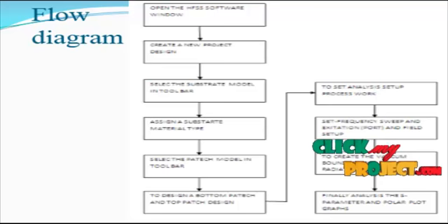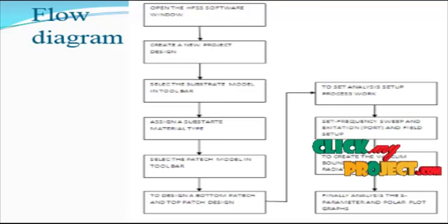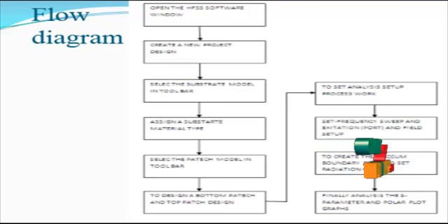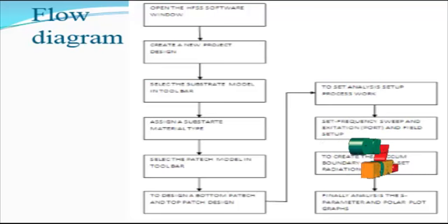We implement the antenna design using the HFSS software. This high frequency structure simulator handles the frequency development and the bandwidth calculation, and all the designs and developments are included in the HFSS software. First we open the new HFSS software and create a new project design in our 3D model based designs. First we choose the substrate model, and analyze the substrate model, the dielectric constant value, the permittivity value, and the dielectric substrate modeling type, all of which are to be noted.